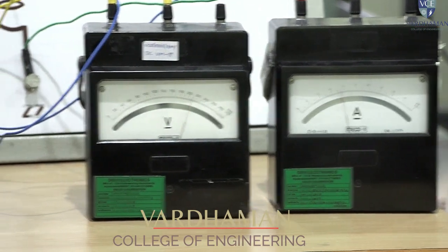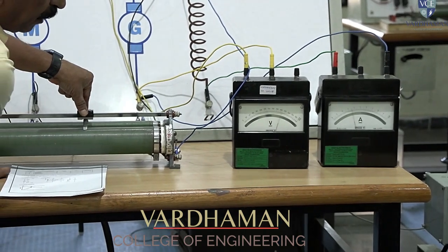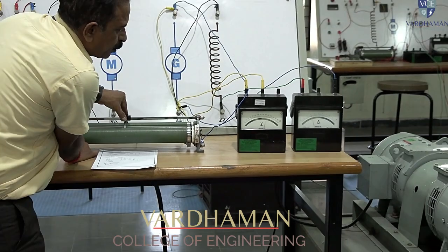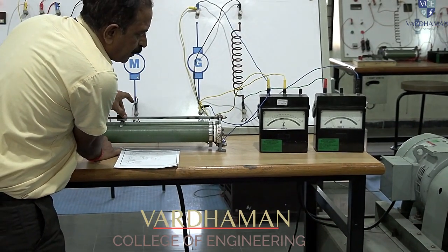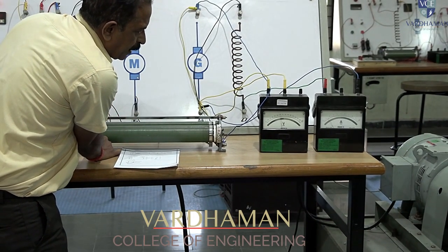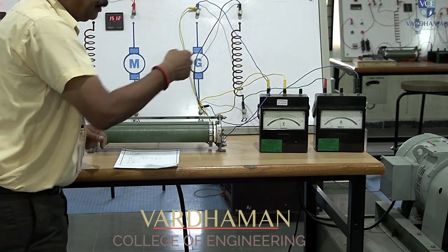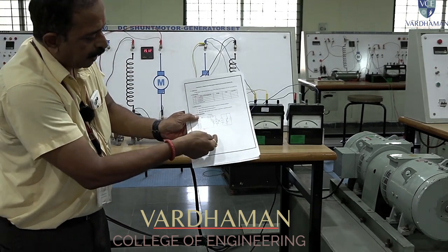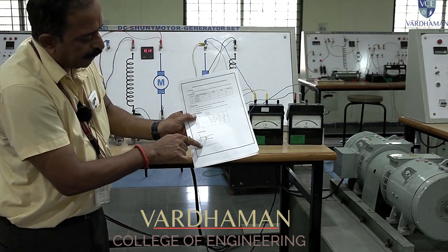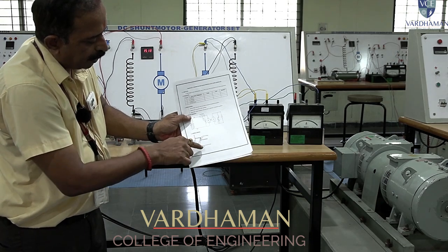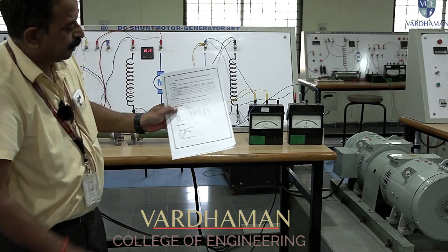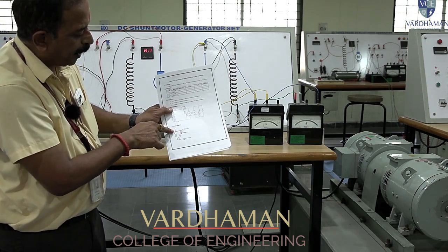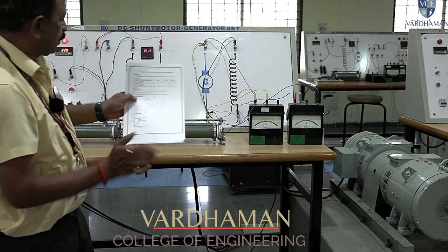The same experiment can be carried out in a decreasing manner also. Whatever the points of current we have noted down, the same points you keep here and note down the voltage decreasing. So like this, increasing values as well as decreasing values. There is a slight difference between increasing and decreasing, which you can observe from this graph, increasing mode and decreasing mode. Voltage value is taken on this axis, field current IF is taken on this X axis. By plotting the graph, you need to take the slope of this graph to obtain resistance, the critical field resistance.